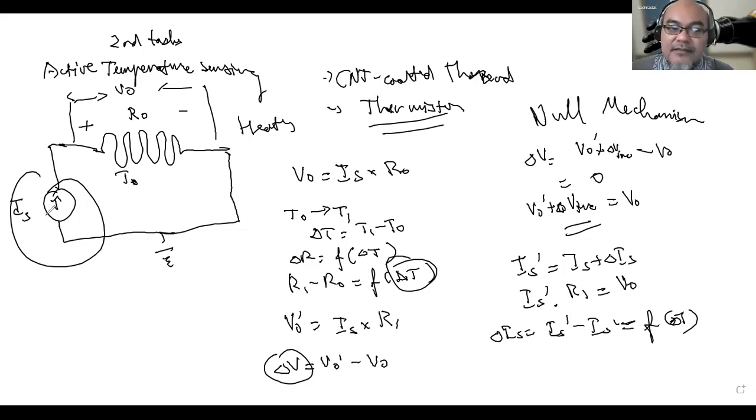It means you know the temperature not by converting it directly using the thermistor formula, but rather from a feedback control mechanism, by the amount of current that you need to inject more or less towards this heater system in order that the output voltage remains the same.